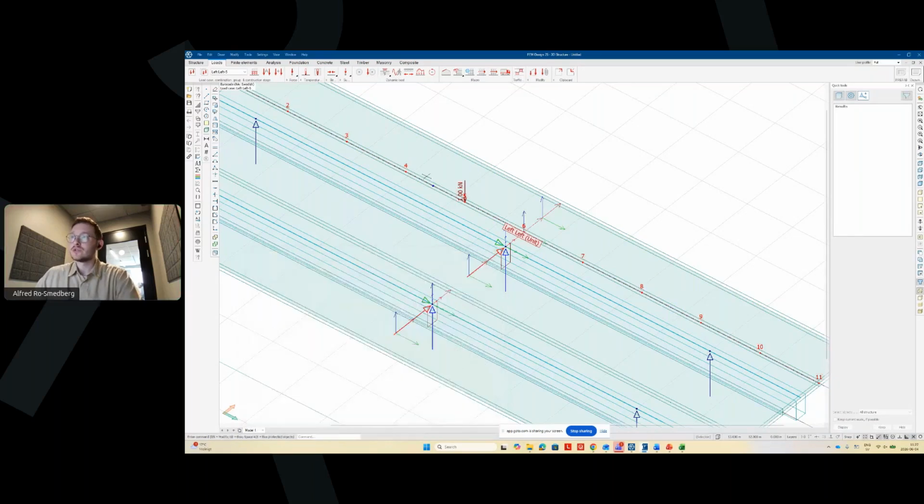A key to remember when you're using the 3D Bridge module, and especially the math generation, when you're generating many results, for example several hundred types of traffic loads, is this: if you run the analysis for just one traffic load result, in theory you can multiply the runtime for that one result by the total number of results you're going to ask for in your final run.